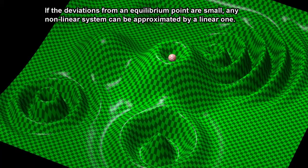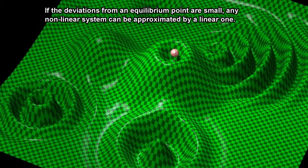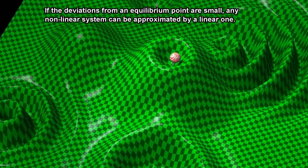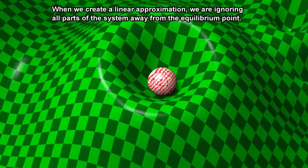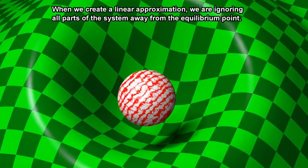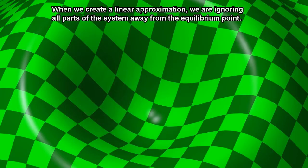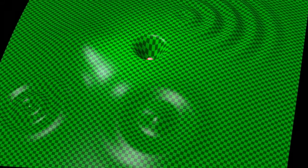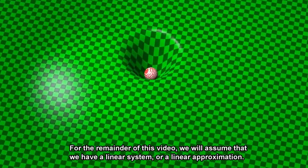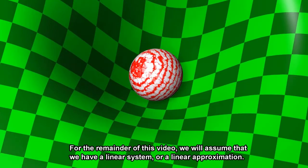If the deviations from an equilibrium point are small, any nonlinear system can be approximated by a linear one. When we create a linear approximation, we are ignoring all parts of the system away from the equilibrium point. For the remainder of this video, we will assume that we have a linear system, or a linear approximation.